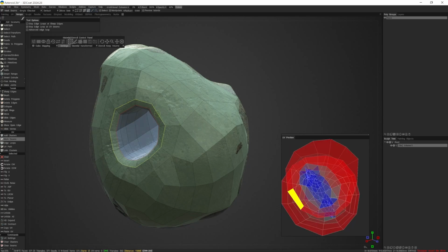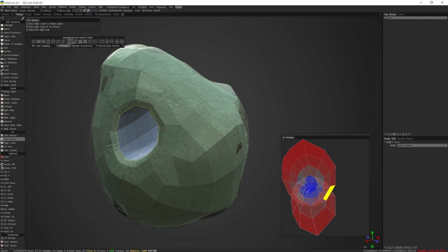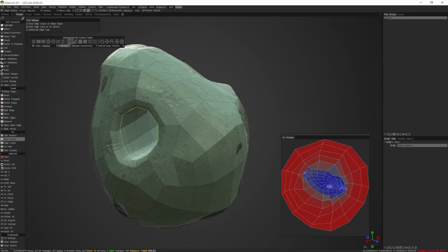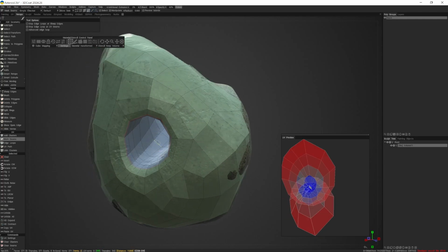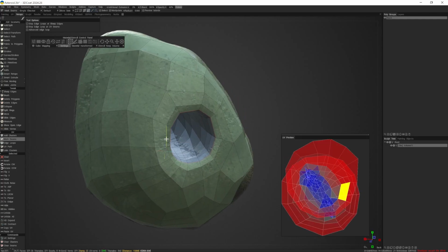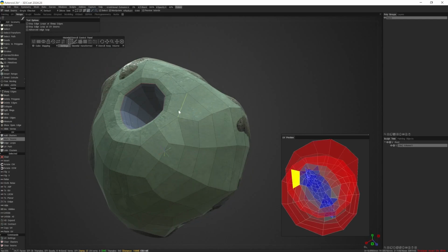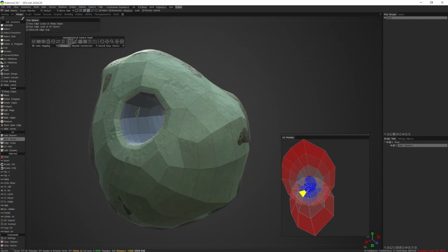Shift to mark a whole seam. Shift and Control to remove a whole edge loop. Okay. So anyways, so we have this. You see, I hover over this, and because I haven't made any lengthwise cut, it's almost just like a tube. It doesn't give us a great unwrap.